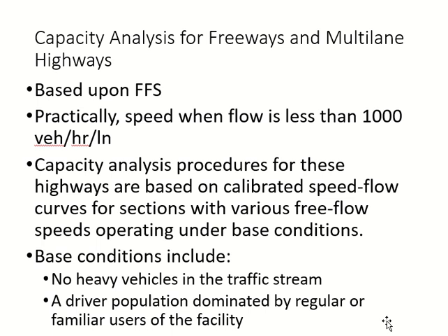They are regular drivers. Okay, so they are familiar with the lanes and the speed limit and the directions and everything. So these two base conditions give us a maximum flow. No heavy vehicles means the slow vehicles, the trucks and buses are out. So that means now the cars will give you more flow because they travel faster. And same thing with the regular, familiar drivers. They know the highway, so they are supposed to be faster than the other drivers.